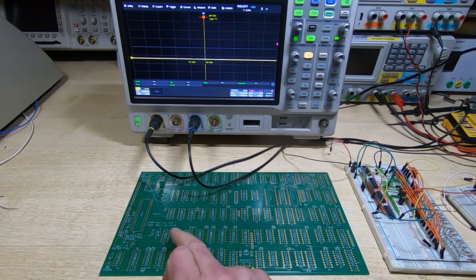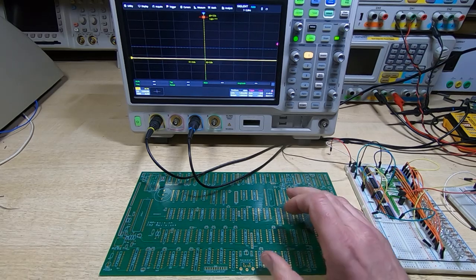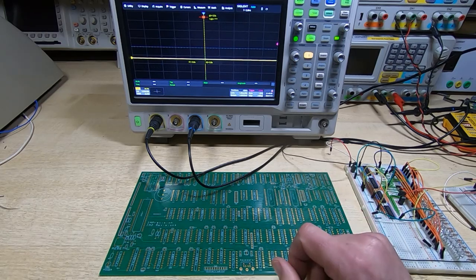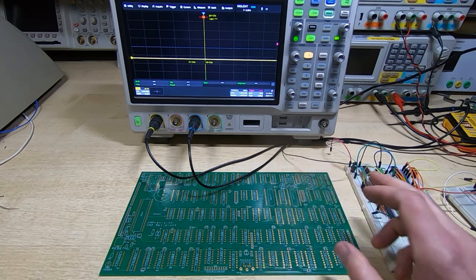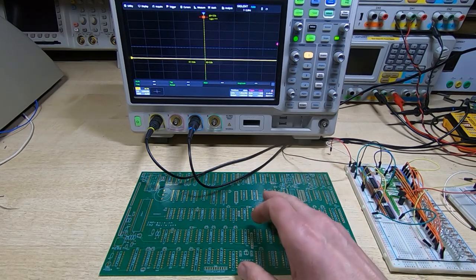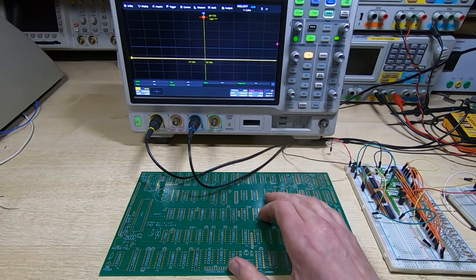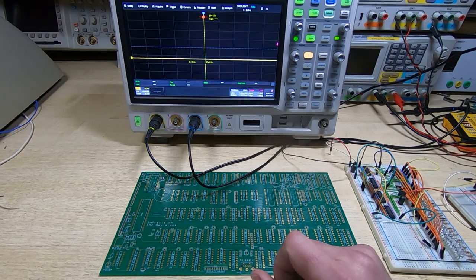The reason being is because there's very little buffering on the data bus, and the Z80s were struggling to drive the data bus. The same was true to a certain extent with the address bus, but there was more buffering on the address bus, so it was less of an issue. So to go any further with the design, as well as adding the required circuits, I also had to completely change the board to add very extensive buffering between the Z80, the data bus and the address bus.